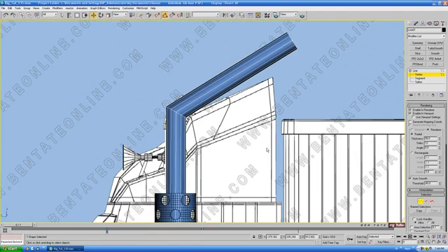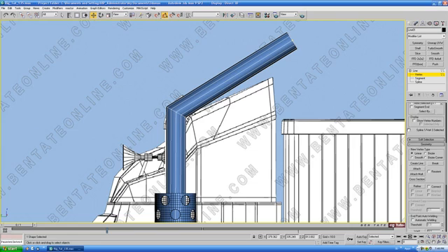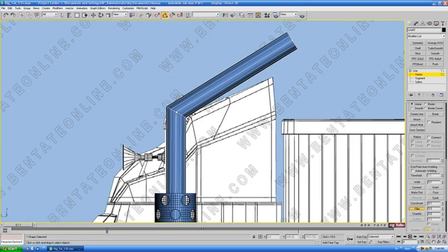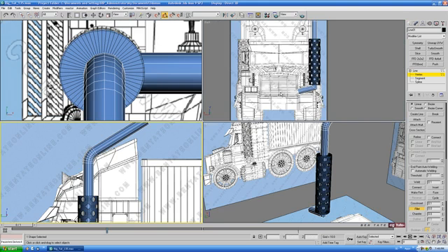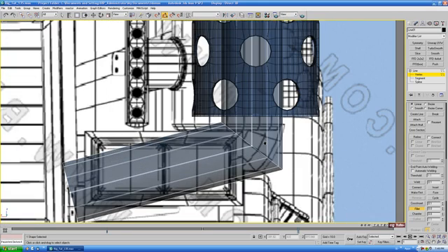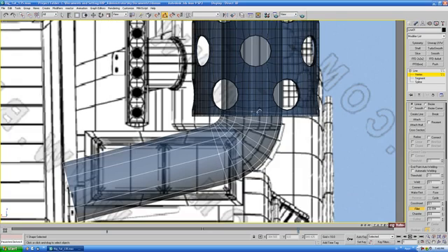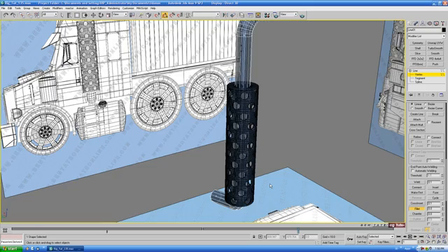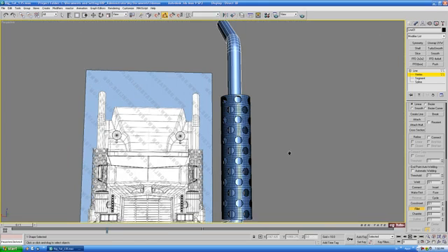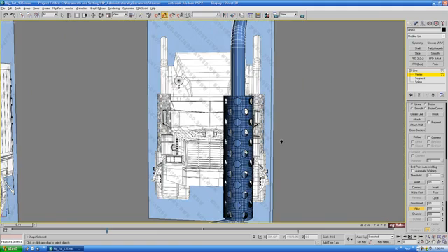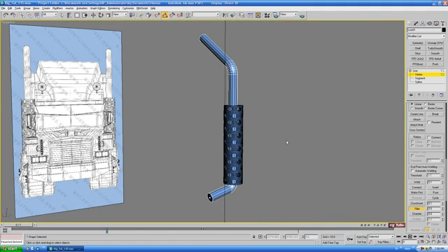Let's go back into the left view here, and we'll just curve this vert over by using fillet. Alright, so go way down in the modify panel here until you get to fillet, click that, and we'll just click and hold down the mouse button on this vert here and drag up. Okay, we'll do it, say about there, and we'll do a similar thing here at the bottom. Okay, so let's grab this vert and we'll just go up on this. Okay, just make sure you go enough that the edges aren't crossing on the inside there, over here. You want to have those spaced out a little bit. Okay, we'll probably need to pull that down a little bit farther later on. Okay, so that's pretty much the shape we're looking for.